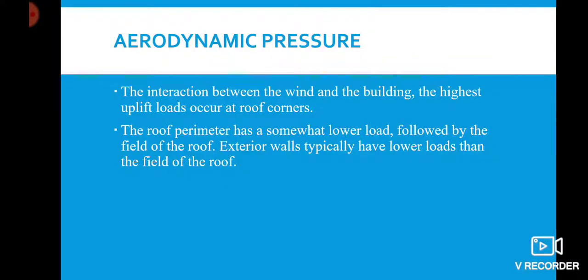However, when the wall is loaded with positive pressure, the entire wall is uniformly loaded. The negative values indicate pressure acting upward from the roof surface and outward from the wall surface. Positive values indicate positive pressure acting inward on wall surfaces. Aerodynamic influences are accounted for by use of external pressure coefficients, which are used in load calculations.